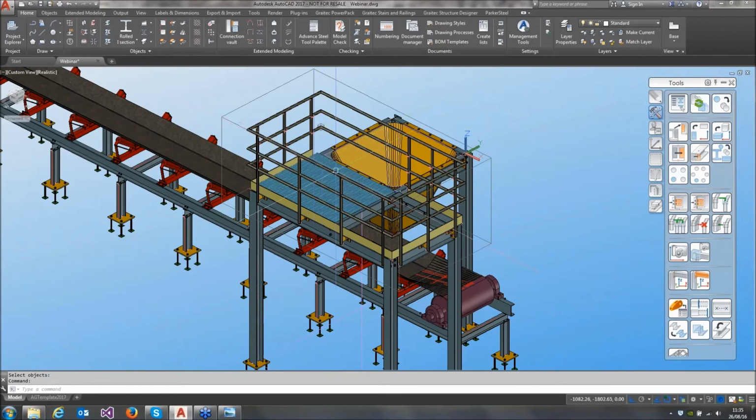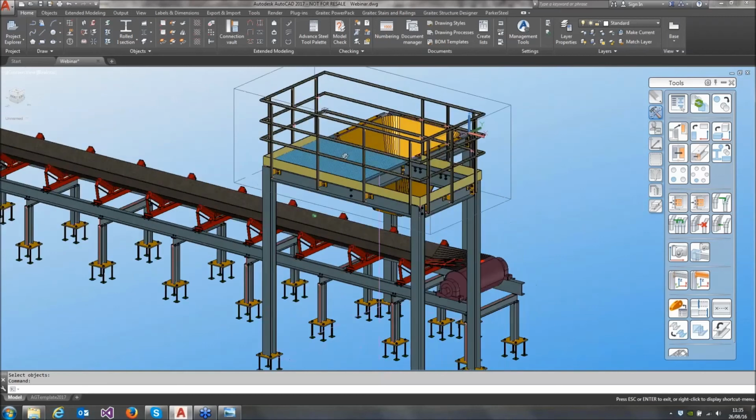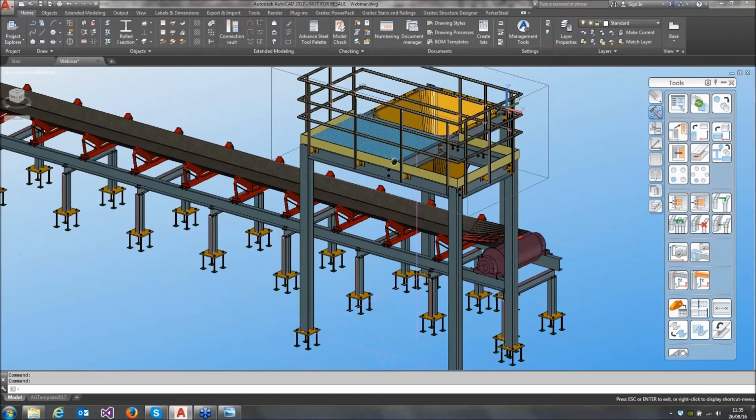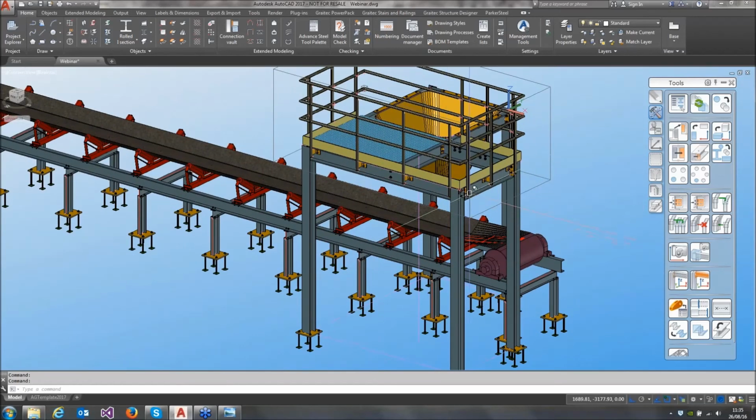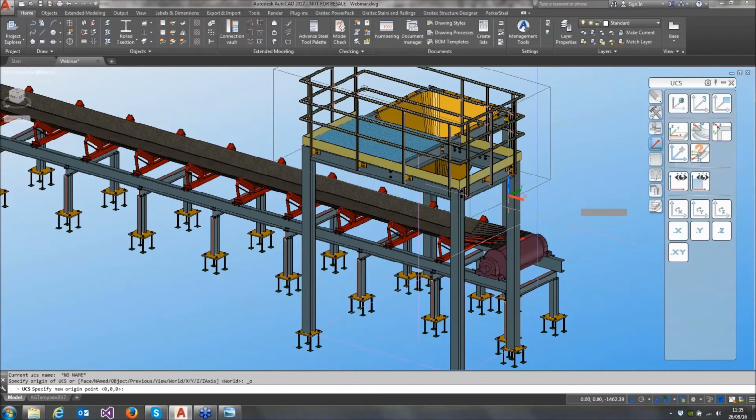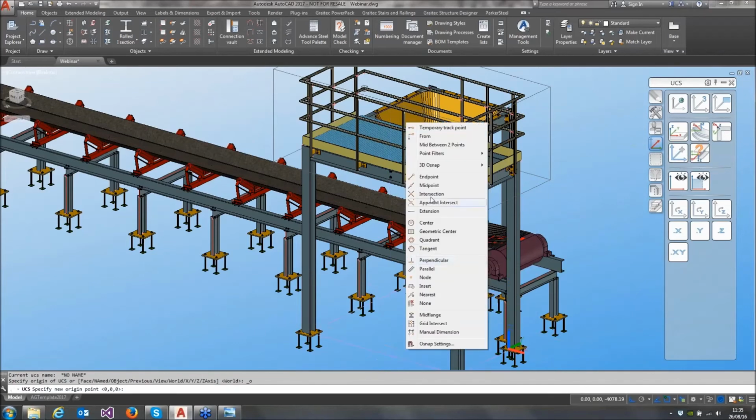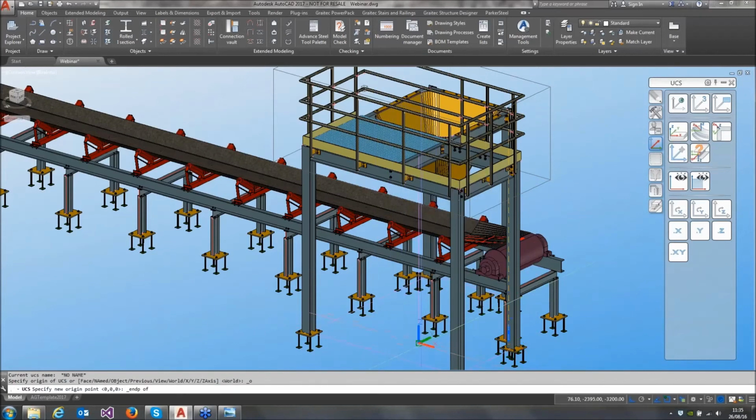Now the last thing we've got to do is tell him how to get up there. You can't just float, so we're going to put a ladder up to that platform. When you're doing a cage ladder, you need to make sure the y-axis is pointing in the direction of the climber. So let's get my coordinates into a recognizable location and rotate them so that y is pointing on the side the climber will stand on. That's it. And now I can use the cage ladder macro from the bottom of there going upwards.